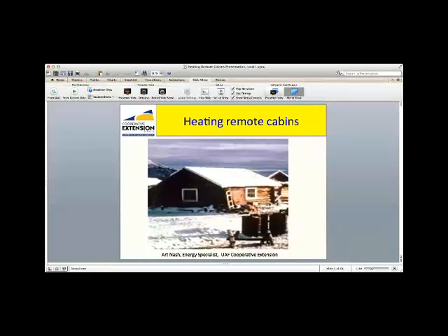And unfortunately, when a house isn't well insulated, the walls, or if it's in a roof, you have a cold roof, it just shows that certain parts of the house are accepting heat and others aren't. This can cause problems in time if there's condensation, especially in the walls with this uneven heat.